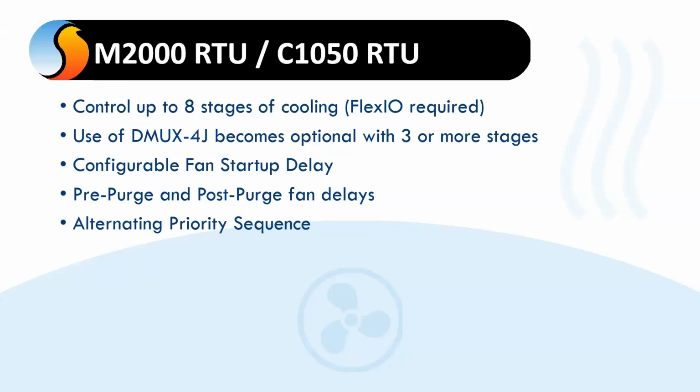But it would still focus on whatever the priority was. If that priority, say your cooling priority and your cooling demand never went away, we're going to be stuck in that. We will never deal with a heating demand. We now have a timer function in there where we can have that time out, and we will actually force a changeover. So that's been something that has been requested.